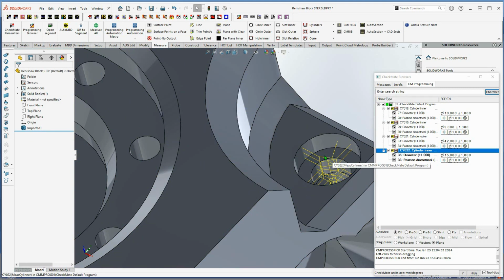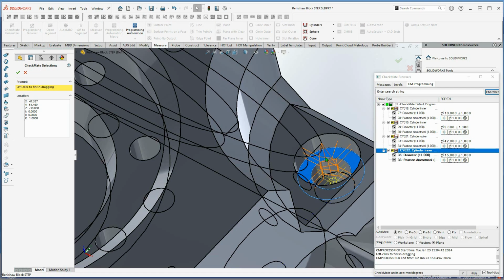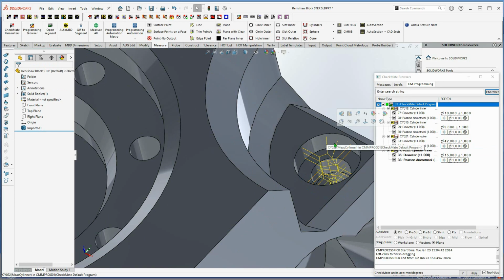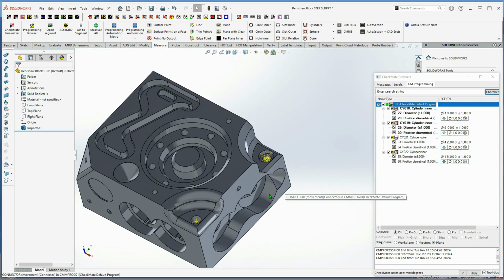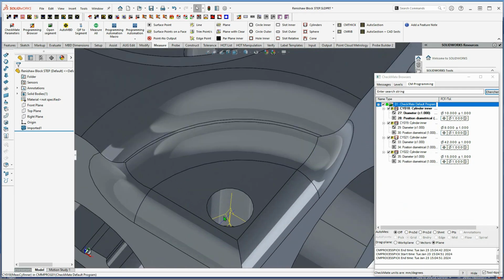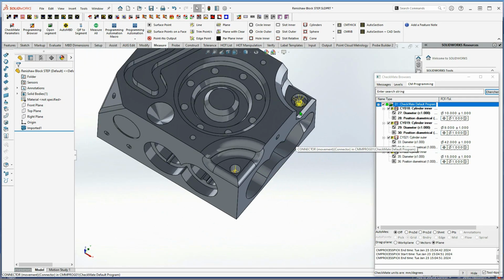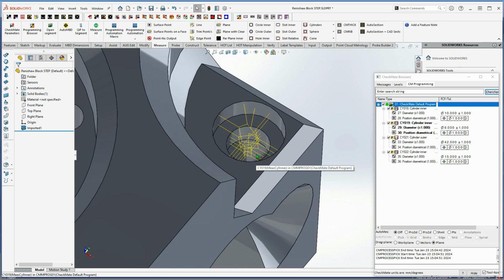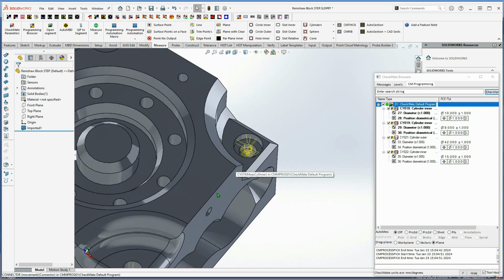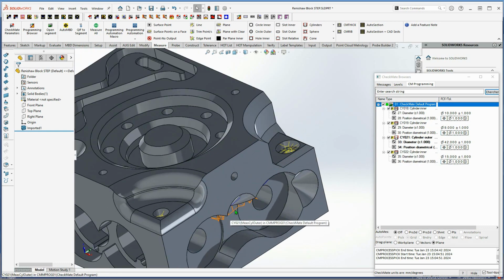And just for fun, the way you add points to these freeform measurements is with the control key, just like you were doing the surface measurement. And if you want to take points away, you can hold down the escape key and get rid of individual points. So, this cylinder is originally as measured. As is this one. This one is in freeform mode because of editing, and this one was born in freeform mode.